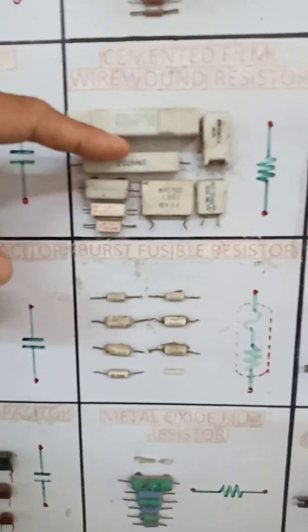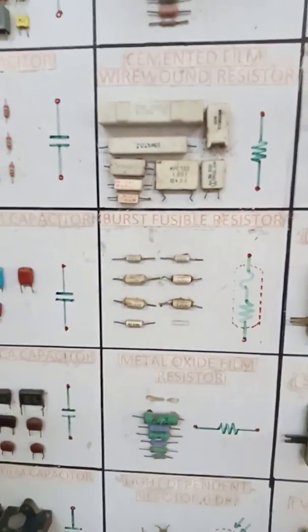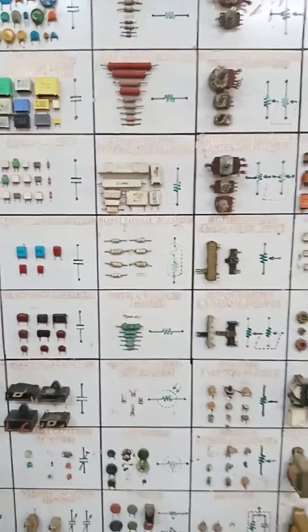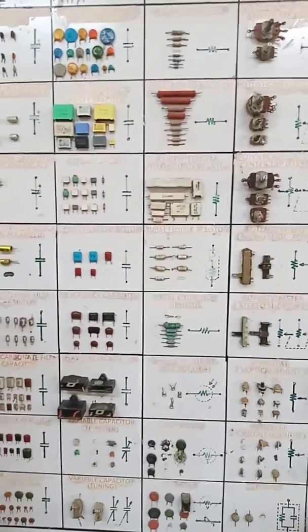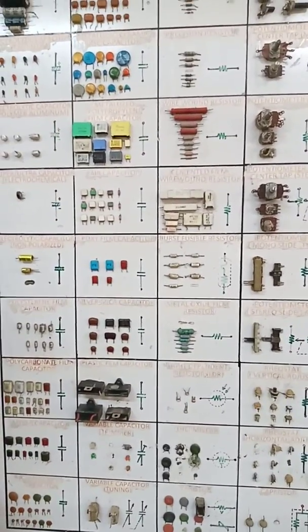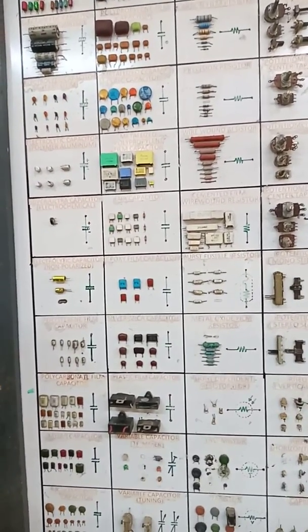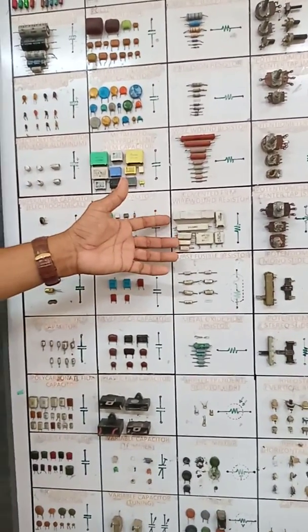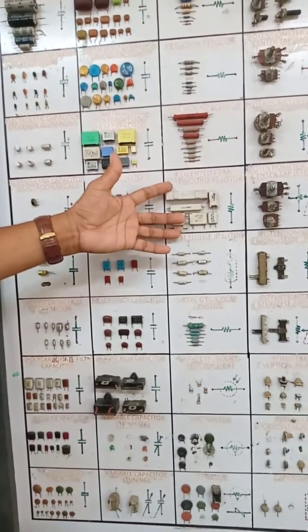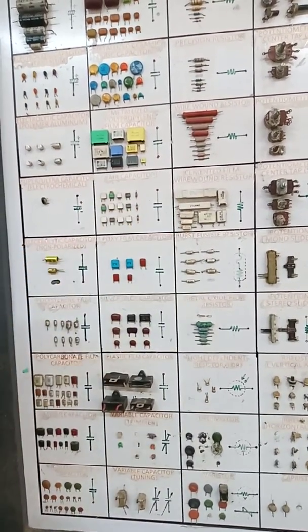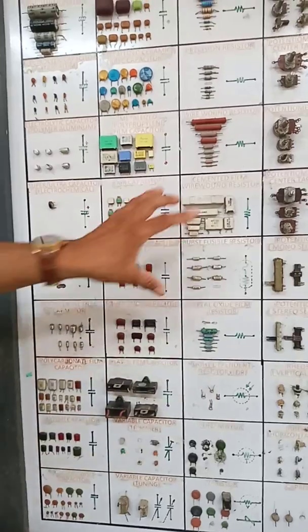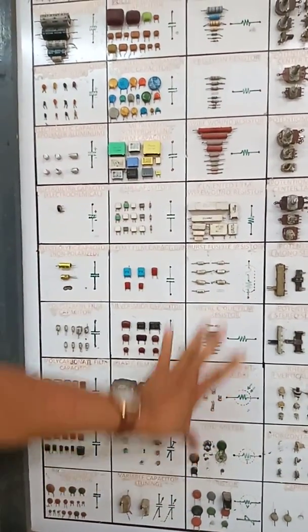It is inverted. Okay, J actually is the tolerance. J, K, M. J is more or less 5%, K is more or less 10%, and M is more or less 20%. Those are the numerical code letters. The letters there are the tolerances, so they are actually given.